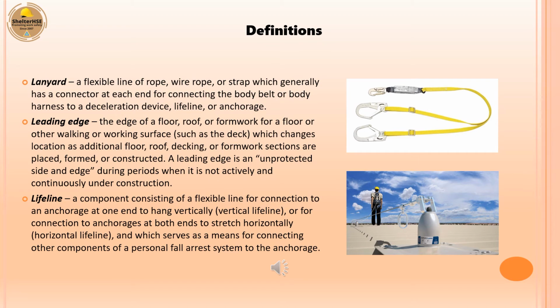A leading edge is considered to be an unprotected side and edge during periods when it is not actively and continuously under construction. Lifeline: a component consisting of a flexible line for connection to an anchorage at one end to hang vertically, a vertical lifeline, or for connection to anchorages at both ends to stretch horizontally, a horizontal lifeline, and which serves as a means for connecting other components of a personal fall arrest system to the anchorage.